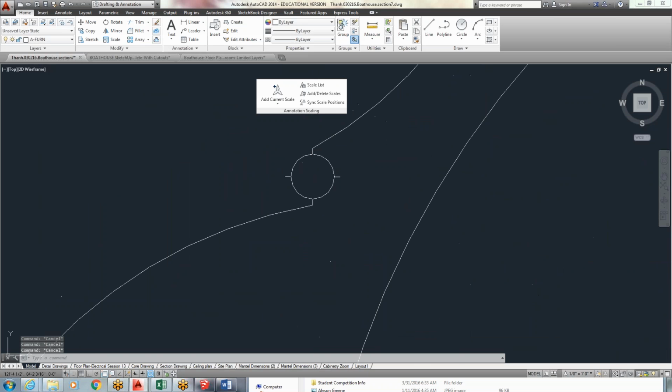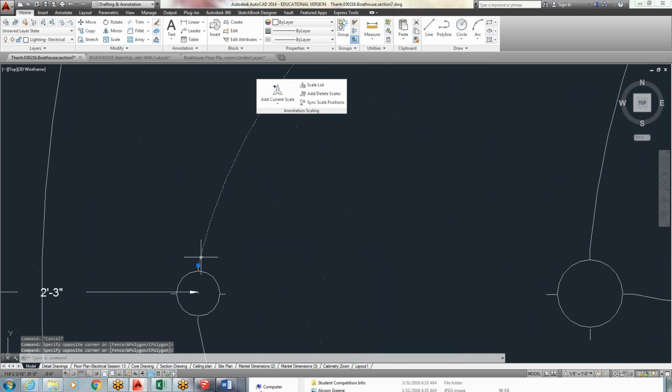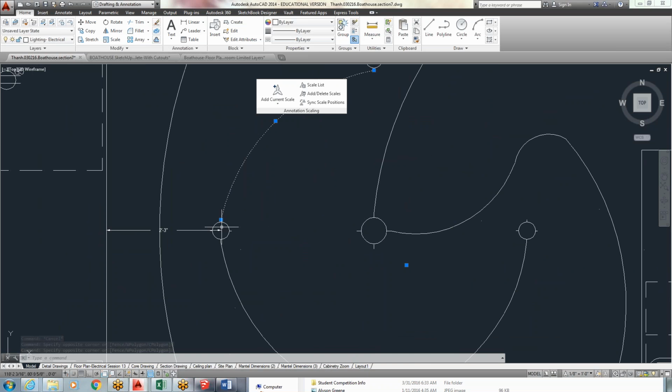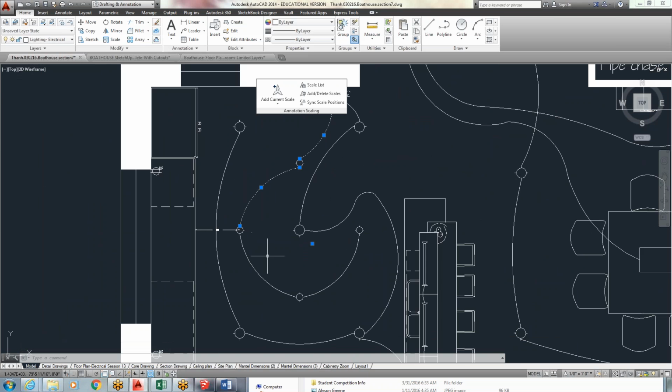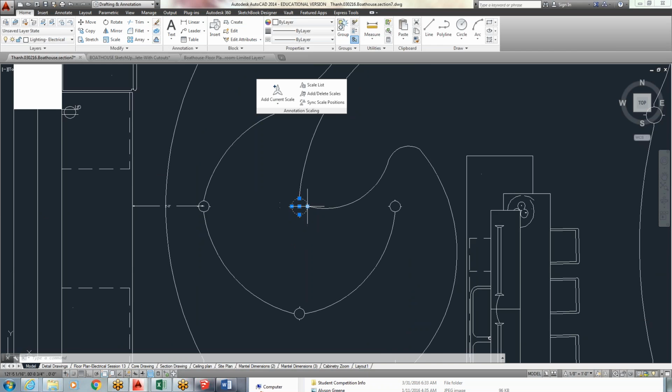So I connected all of my lines at the centers of these ends to my lights, my can lights that I drew. And really, for the most part, this does signify a can light. It'll just be the circle with the radius of whatever your true can light is. So for 6 inches, it has a 3-inch radius, and for 4, it has a 2-inch radius. But sometimes you can make things up.